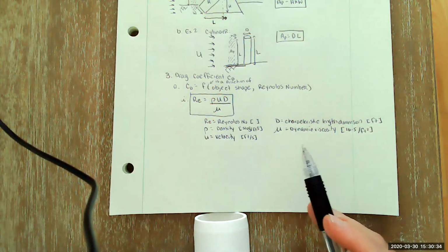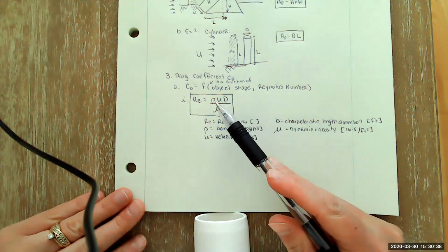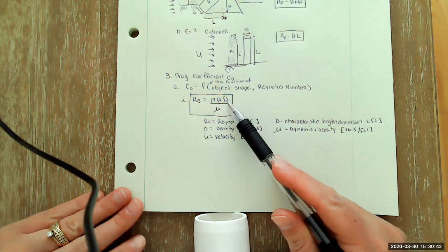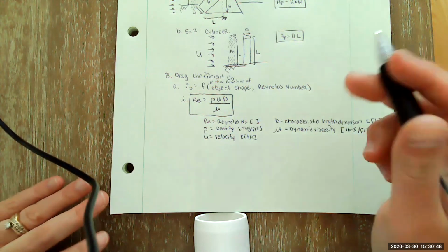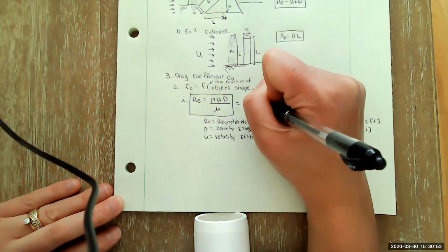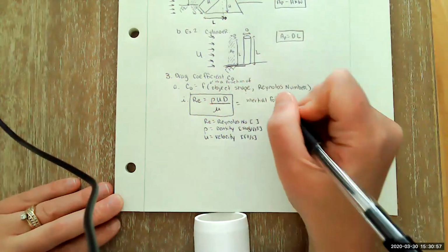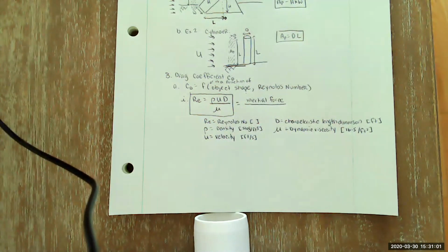And this is a really useful tool. Another way to think about this Reynolds number is if we think about the density times the velocity times how big this fluid column or fluid shape interaction is. That's kind of like the inertial force, or it is the inertial force, divided by viscosity, which is another way to represent friction in fluid flow.